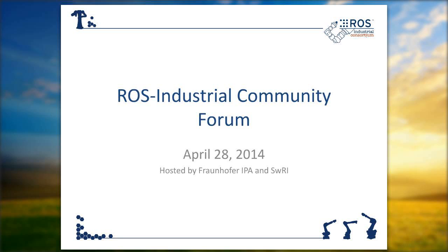In fact, in the end, all of the controllers that are implemented already in ROS control are in a way or another a custom controller. So you could write a controller that might be, for example, robot specific, that you cannot generalize across other robots because it depends on interfaces that no other robot but yours has.